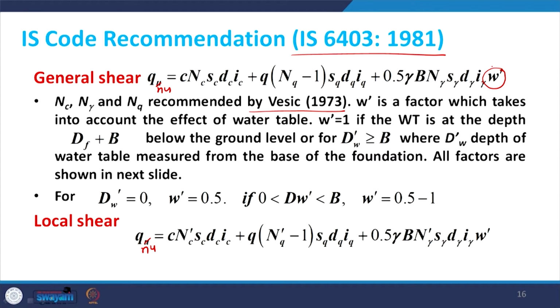Now, here is also a little difference. When we discussed Terzaghi's theory, the effect of water table was in the second term as well as in the third term. However, in the Indian standard code it is only in the third term. So, let us then discuss the effect of water table.